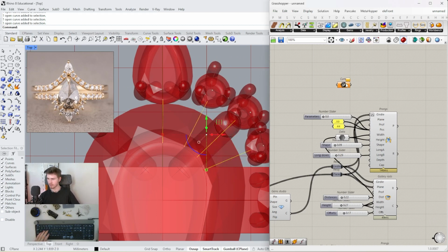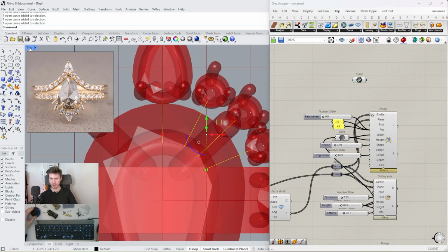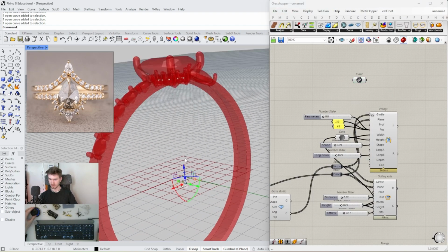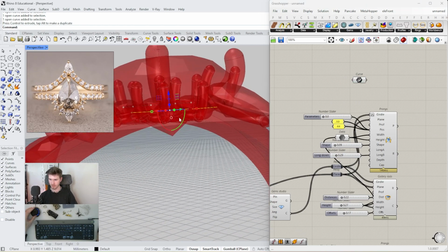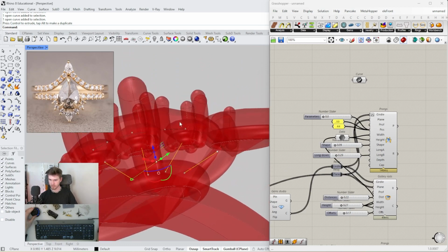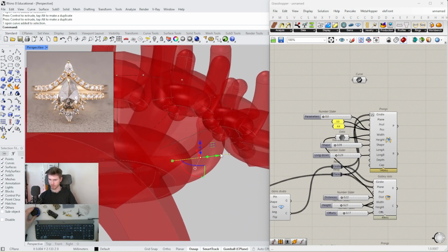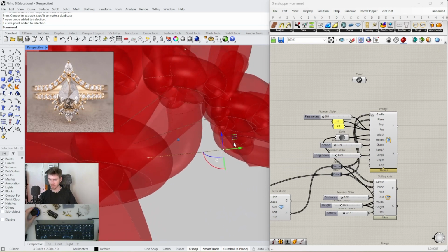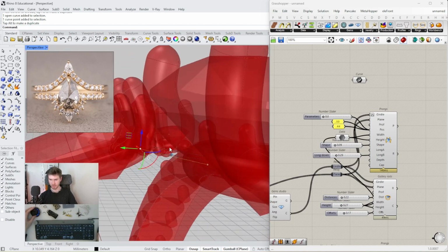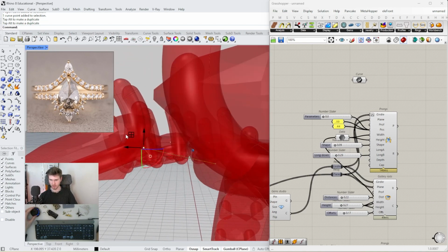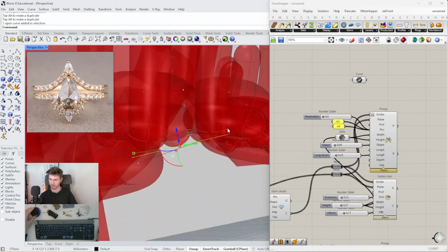Let's internalize these in Grasshopper by just setting multiple curves, and then we'll go back into perspective and actually move these into place, because again, they're always going to sit on that XY plane. So let's bring these up, and once they're in a relatively good position, we can click on them and actually edit the control points and start putting these curves at an angle if needed. So we can do this to connect any curves together just manually.